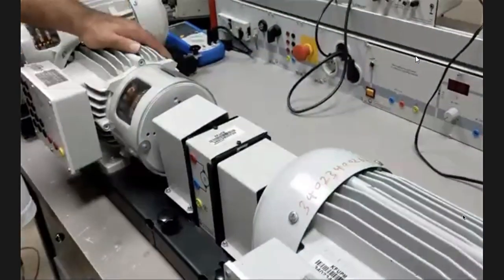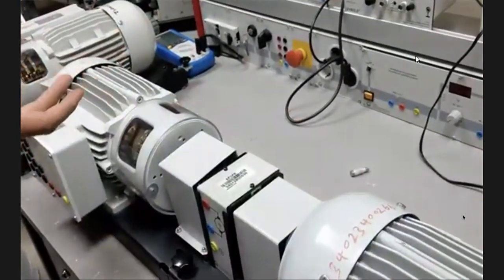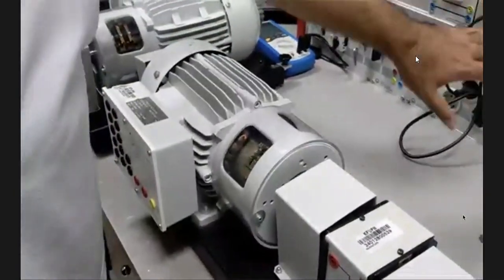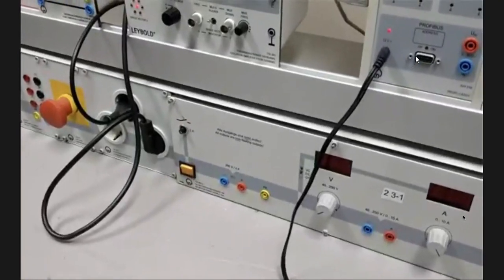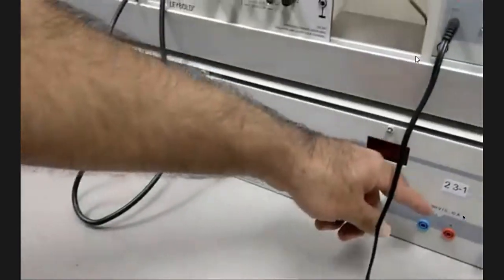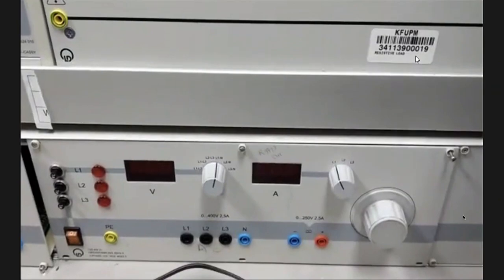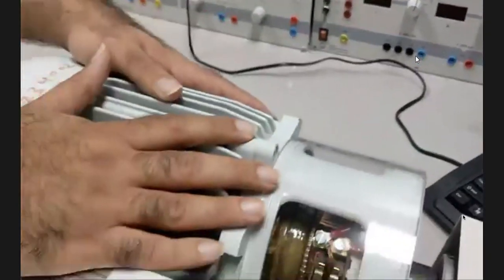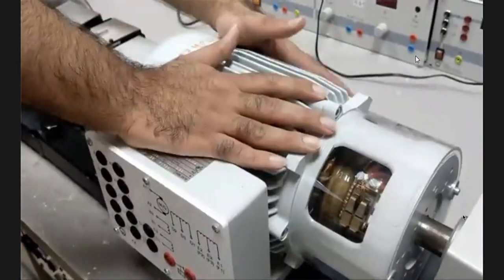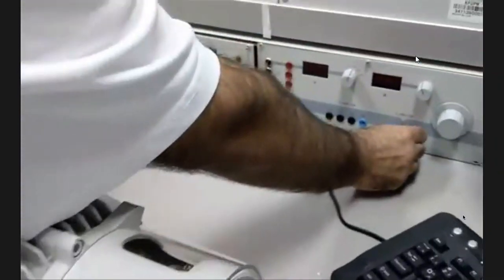And as we did before, to do this experiment, what do we need? We also need a DC supply, because we will connect this as a DC motor. So we will need a DC supply to supply the motor. This DC supply will be connected to this motor, and these DC terminals will be connected to the field of the generator. You remember we said we will do a separately excited DC generator and the open circuit characteristics. For these, we will use this DC supply.